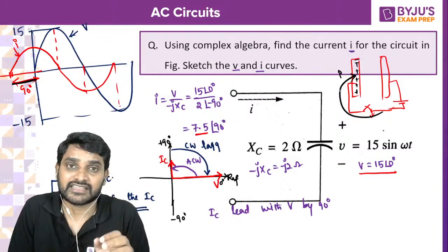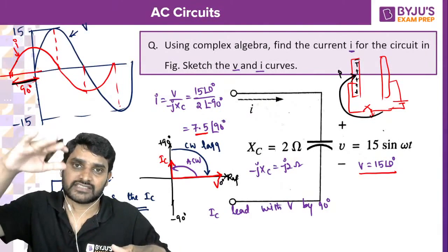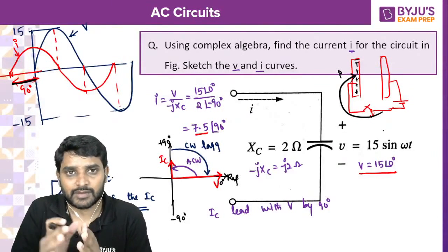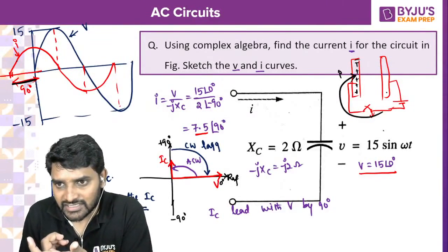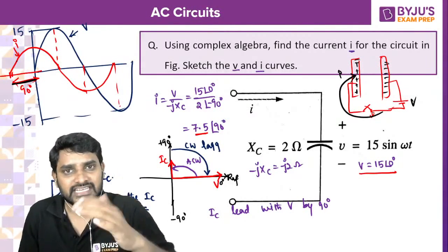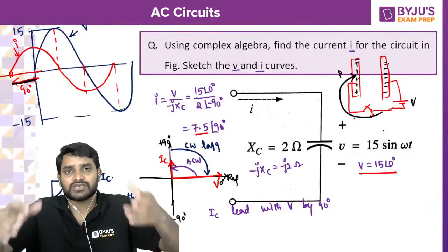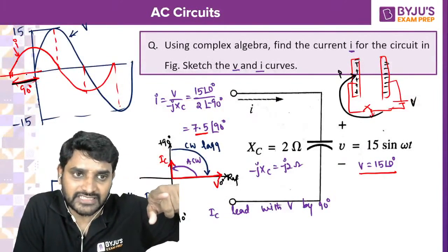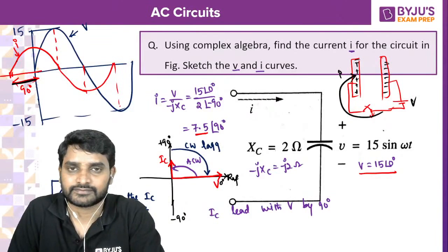That is what we say: a capacitor will oppose sudden changes in voltage development. It is not charging to complete supply voltage suddenly. It is taking some time. So it is accepting a huge amount of current, and then it is building the voltage. So current first, voltage next. Quite opposite to inductor. Is it clear?